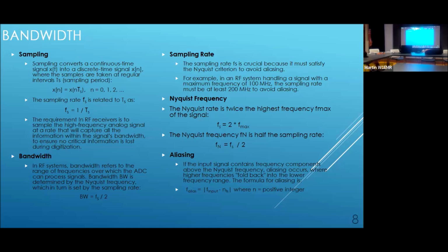That's awfully difficult to achieve in any kind of an LC filter. But guess what? This is a computer, and you can recycle this thing and go through a fast Fourier transform, and you can actually get a digital filter that does a reasonable job at 60 hertz bandwidth. And it's perfect for these circuits, okay? So here we have some simple formulas, okay?